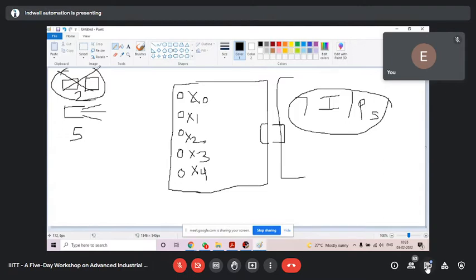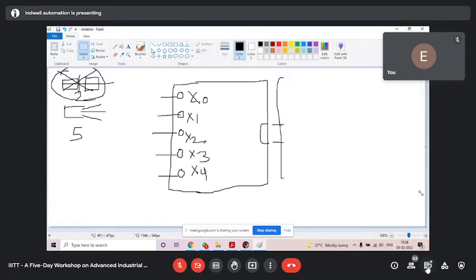Be very clear. Because if you have to use these two and five sensors, you will have to purchase one extension unit. And you have one HMI also in your project. So better, what you do is not connect these two push buttons, but connect all sensors to your main unit. You have five sensors, connect all five sensors. But you will say, how shall we do start and stop? You are correct. How shall we do start stop? Let me show you. We have not connected start stop push buttons, but we can do start stop.